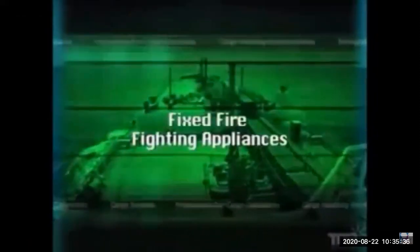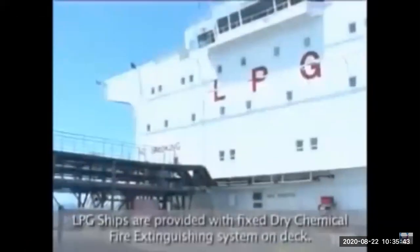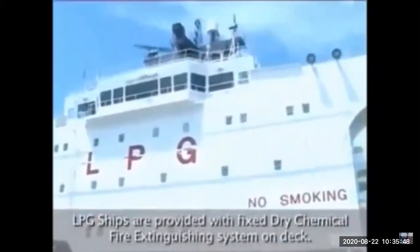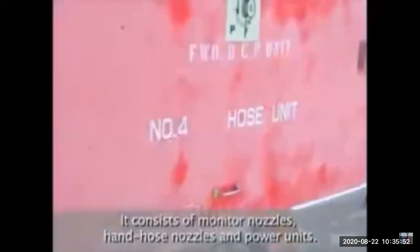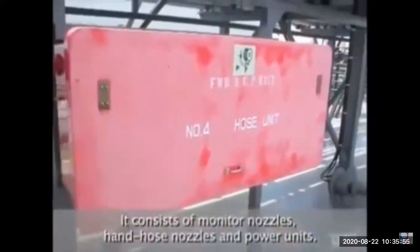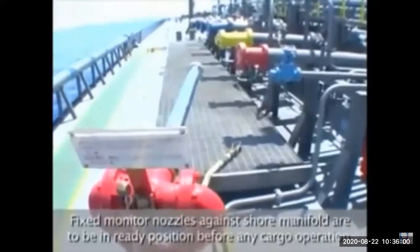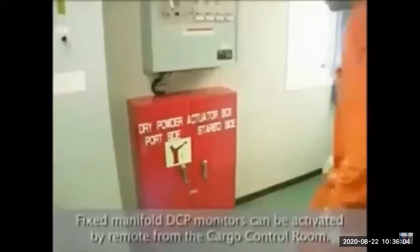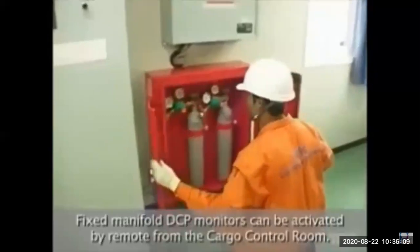Then you have the fixed firefighting system on the gas carrier. Generally, we have the dry chemical powder system. The LPG ships are provided with a fixed dry chemical fire extinguishing system on the deck. These are the foam monitors for the fixed firefighting. And then you have the portable hoses also, and fixed foam monitors from the manifold, always ready. Then you have the pilot activating bottles.